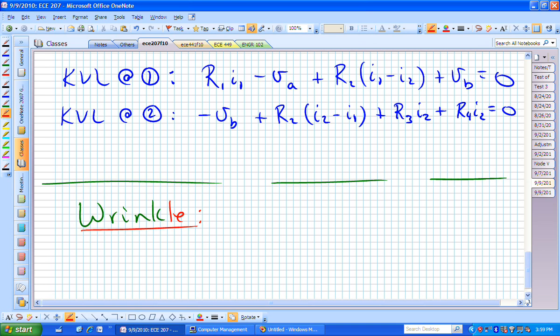Question? For the first portion, it has 2 voltages. How do you write that part? Is that standard? Do you have both voltages in one thing? So the question is, what do you do with those 2 voltages? Now you have actually 2 independent sources. They could be dependent. In this problem, there are 2 independent sources in the same mesh. Those will just be 2 independent sources, and they will appear on the right-hand side. Their sign on the right-hand side depends on how they are helping or hindering I sub 1. In this case, if they were put on the other side, algebraically, you would just have V sub A minus V sub B. And those would be given sources, whatever those are given to be.